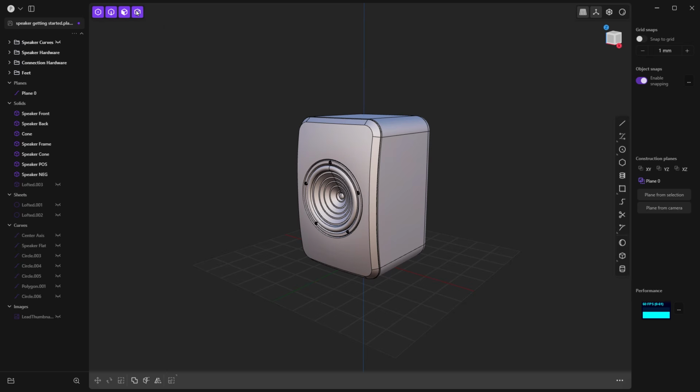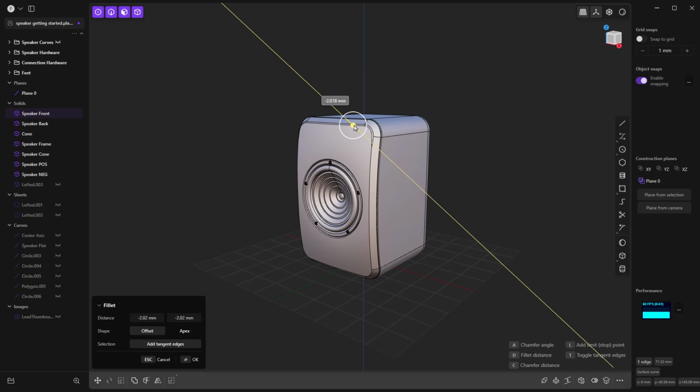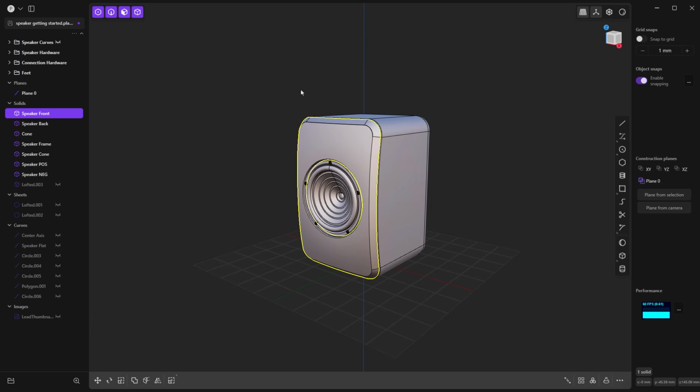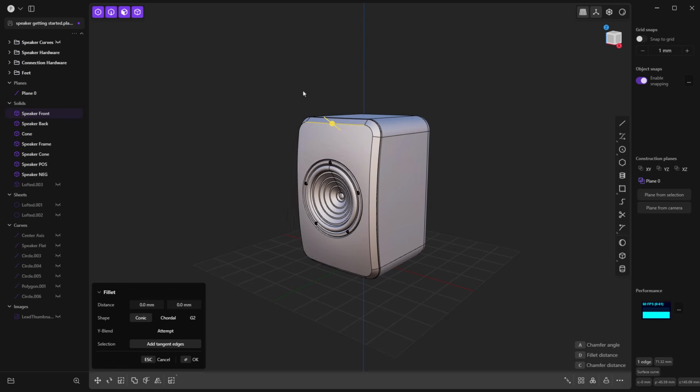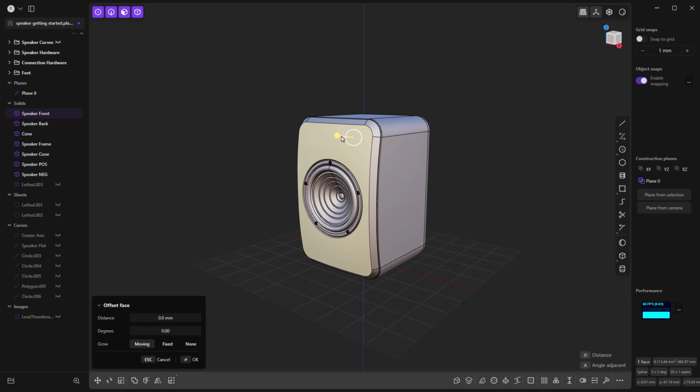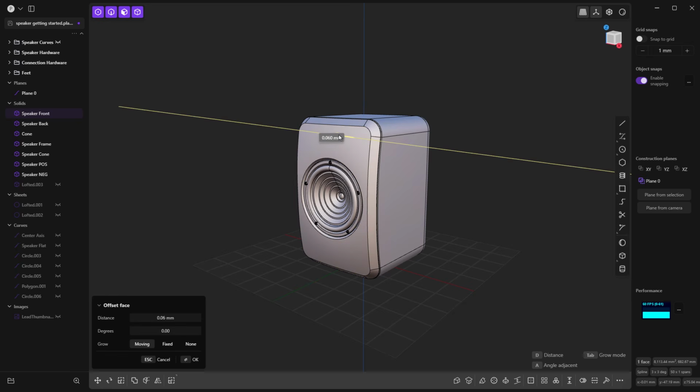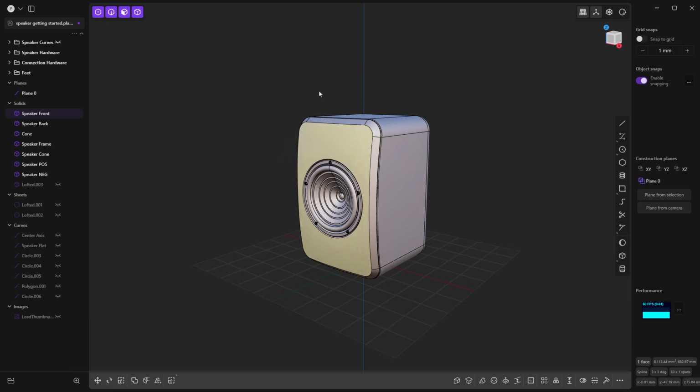The body can be a surface body or a solid body, but in this case, the reason this is important is because the default workflow, if we've got everything selected, is to first select a body, and then we can drill down from there by selecting, let's say, an edge, and then applying a fillet or a chamfer to it, or what we can do is we can select a body and then select a face, and then we can manipulate the face by pulling or pushing it. And these are the general workflows.